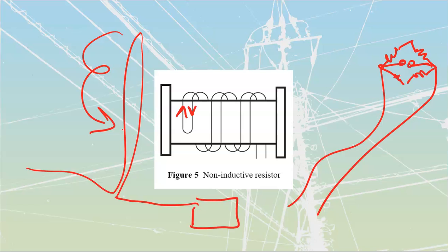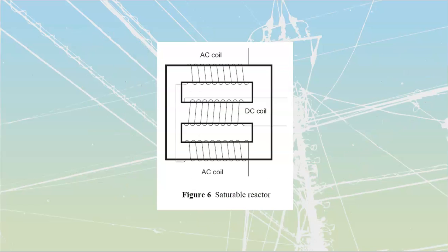The last section that they talk about as well is what we refer to as a saturable reactor. Saturable reactors are a way that we can use the magnetic domains inside of a component to lock down the amount of inductance that I'm going to have. L is equal to N squared mu A all over top of little l. And we talked about how we can have variable inductors before. This is a form of variable inductors.